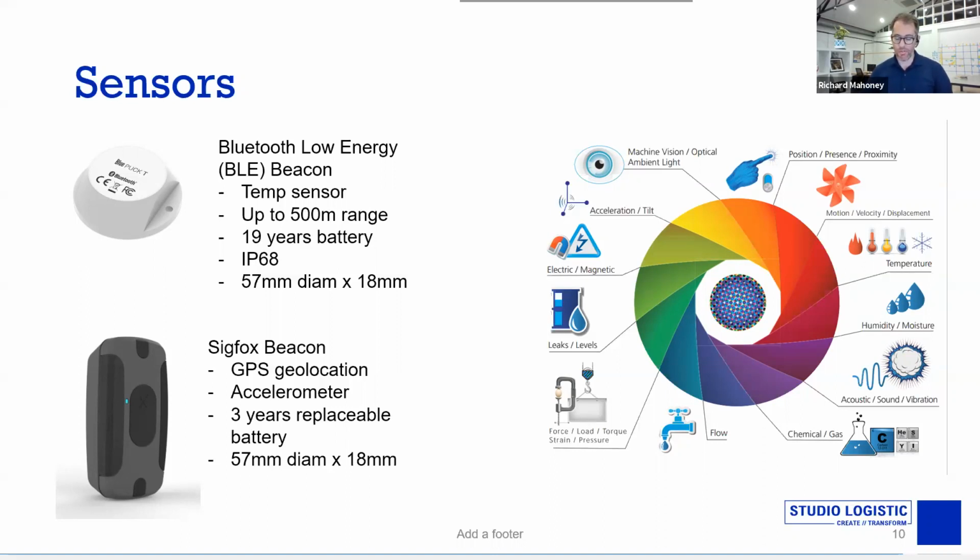This actually leads on into something that's called edge processing, which is, let's say you're interested in doing vision processing or something like that, which is quite processor hungry. If you were uploading a stream of video, that would be quite data hungry as well. The idea of getting that done in the sensor and just sending the bit you're interested in off down the network is what edge processing is about. So I think you start to see that there's a balancing act here between data bandwidth and processing on the device or near to the device that has to be worked out in terms of the application.